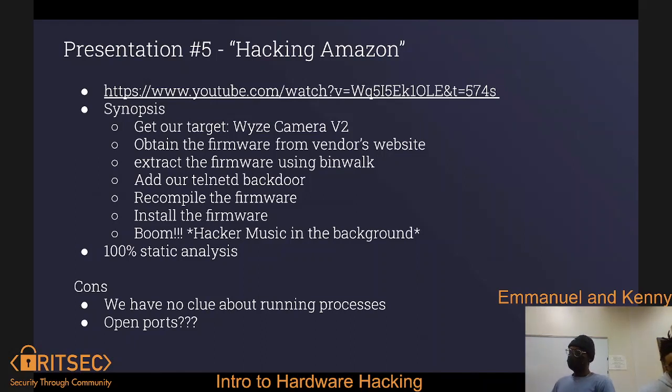At the beginning, I got this camera just for myself. I got the firmware from the vendor and just did some binwalk and extracted the firmware, got the source code of the stuff using just static analysis, so nothing with the hardware. It was pretty cool because you got to see the file system and what a firmware looks like, but it doesn't really give you full information about what's running, like runtime, what processes and what ports are open. So to take that to the next step, we decided to do this, break it apart.